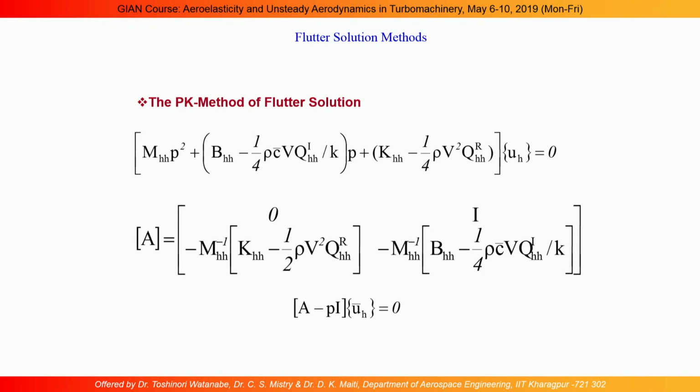For that velocity and mode 1, what is the k value? B is known, B is the semi chord, k is omega B by U. A priori you calculate the complex unsteady aerodynamic load in the k domain, for a set of discrete values of k.